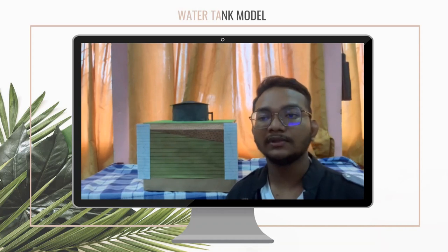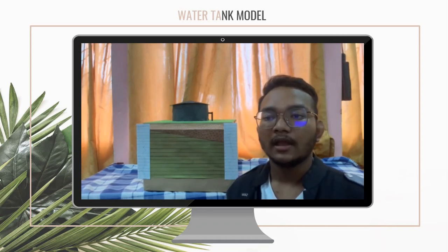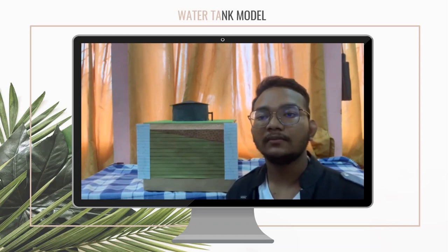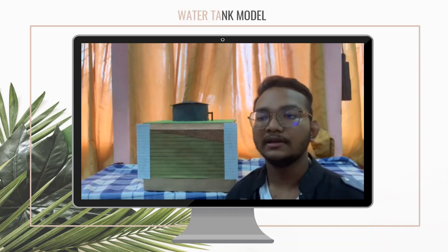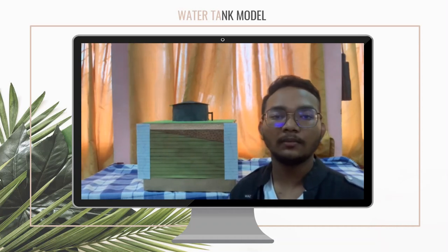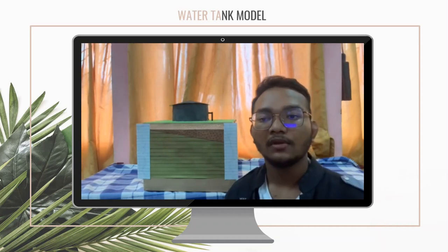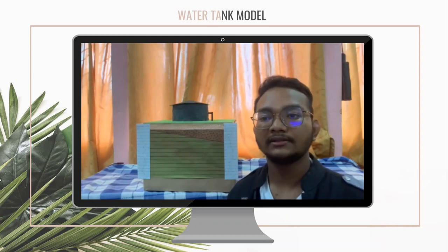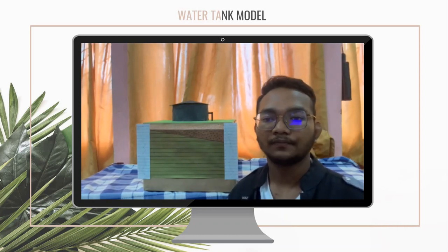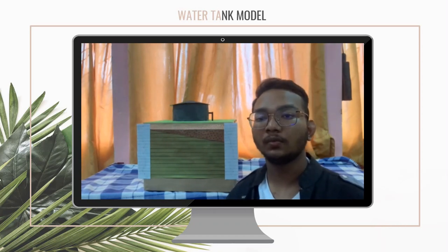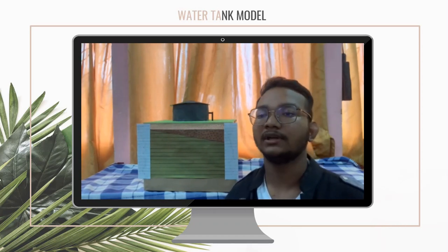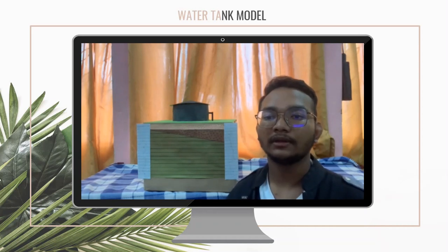Clay soil is commonly referred to as expansive soil because the interlocking between particles is less when the soil is expanded. The density of the soil will drop as a result. Soil shear strength will deteriorate. In our calculation, the soil profile in borehole 1 is more appropriate for the construction of the water tank based on the calculated vertical stress.